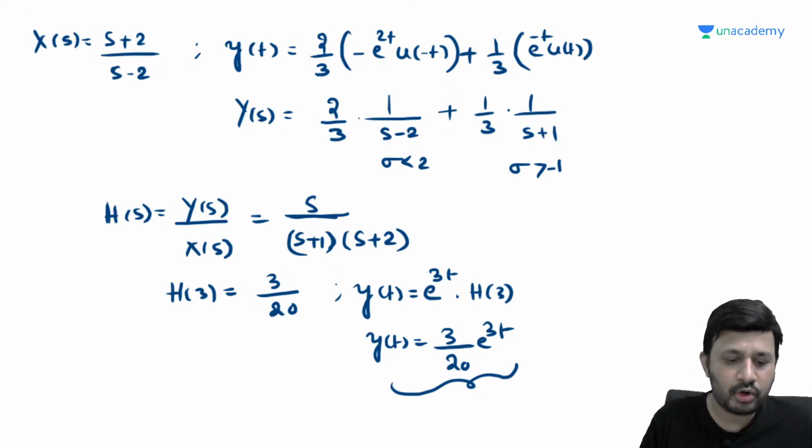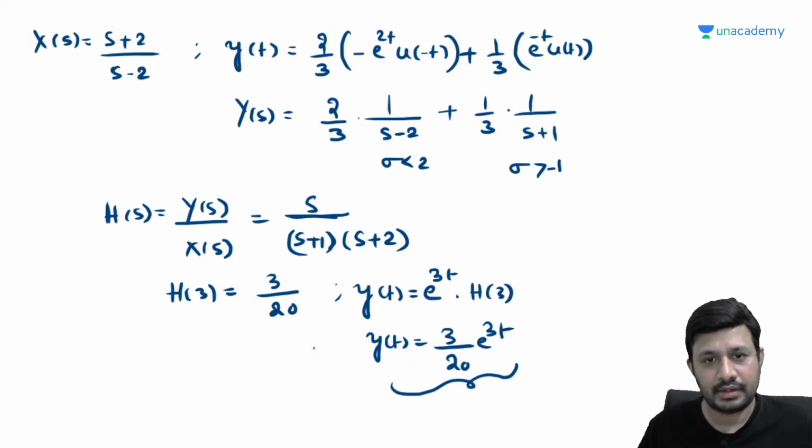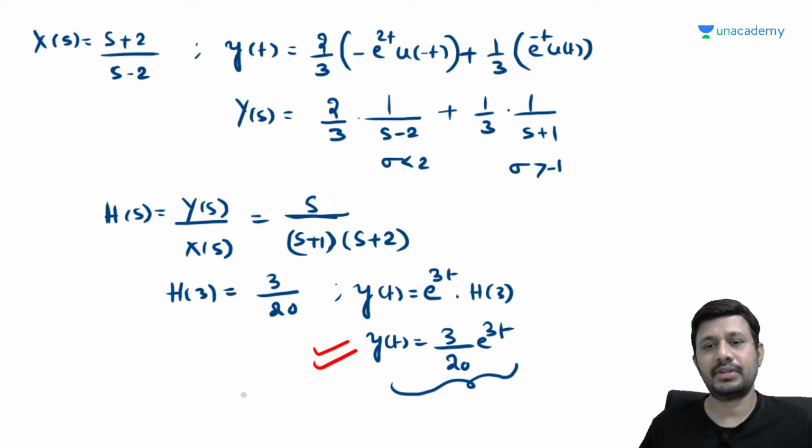A problem, and an important model as well. Whenever you are given everlasting signals as input, go for the Eigenfunction property, because we cannot find the Laplace transform for those signals. Hope this is clear.